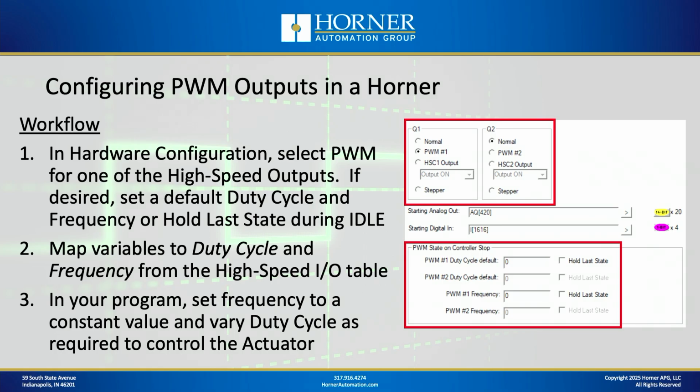Now, if you want a default frequency or a default duty cycle for when the controller's in stop mode, or if you want to hold last state to the last frequency and the last duty cycle when the controller goes to stop mode, then you can configure those as well.